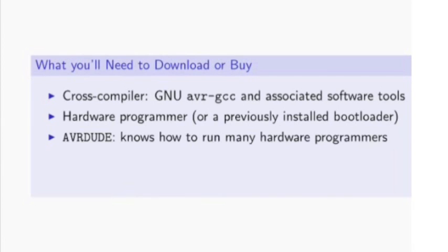On the laptop side, the standard these days, everybody's using AVR Dude, which knows how to talk to a wide variety of hardware programmers, from your Arduino being used as one to 5 wires hooked up to a parallel port. So if you have a hardware programmer, chances are good AVR Dude knows how to speak to it.